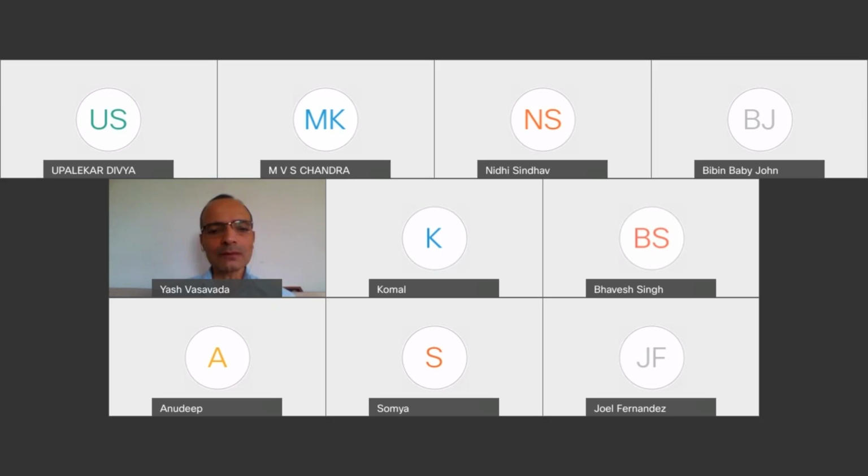Sir, if n is the total number of antennas, we divided into sets, like k sets of elements, for economical reasons. Correct. So Joel captured the essence of it. The motivation was coming purely from the cost-cutting perspective, but it's a major motivation, and that has driven a lot of research into implementing massive MIMO systems in an economically efficient manner.